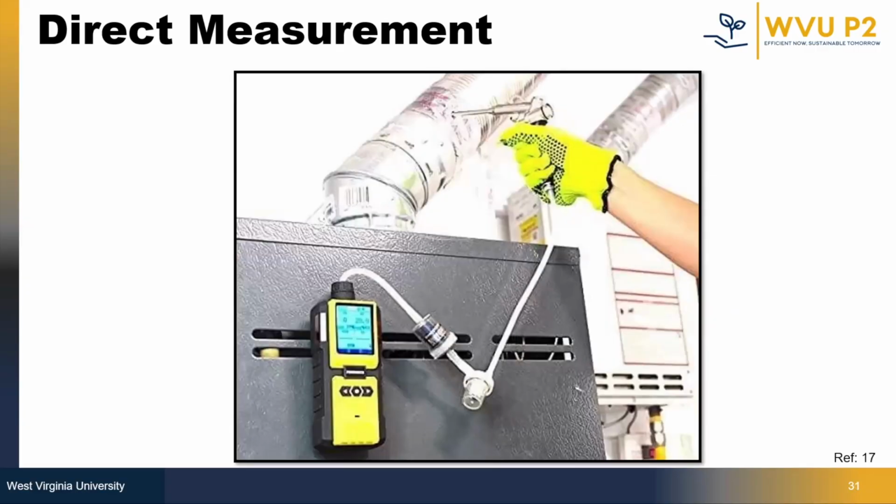So the measurement from a combustion analyzer, along with software like MEASUR, can be used to determine the air to fuel ratio and calculate potential energy and cost savings from making adjustments to the boilers. After measuring the ambient temperature, combustion air temperature, stack temperature, excess air and emissions using the combustion analyzer, MEASUR's flue gas tool can be used to determine the amount of excess air.